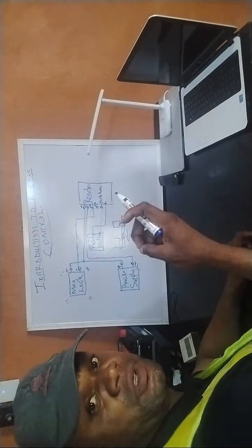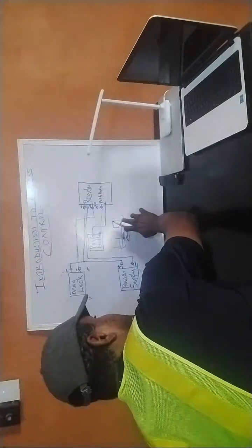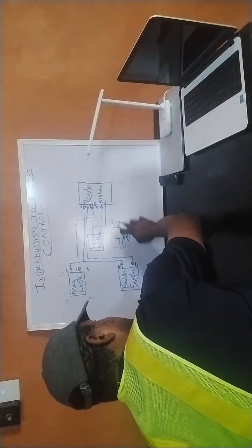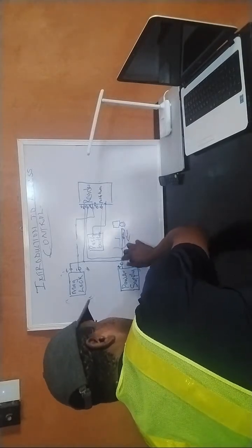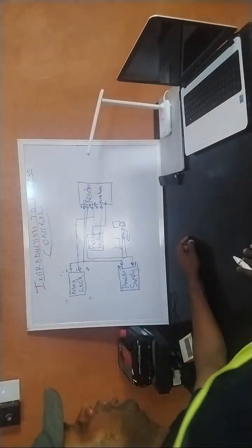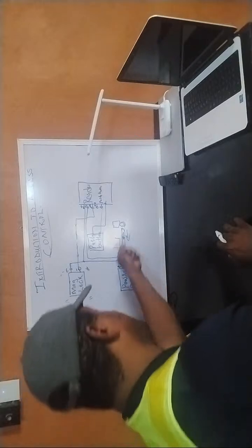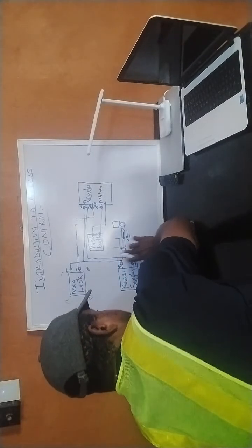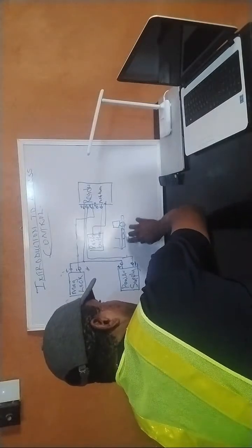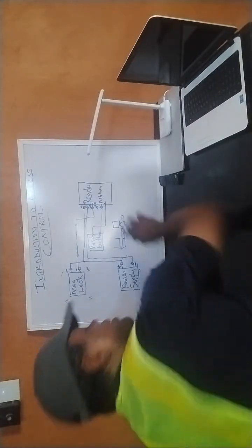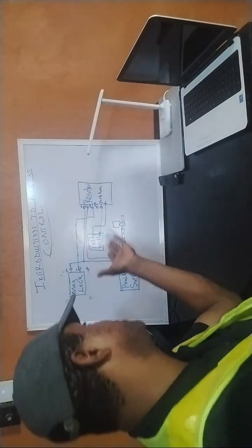For those few seconds that it is pulled out, it's no longer in this place. When the counter elapses the time, this one is pushed back, it returns and goes back into this. So that's how it works for strike lock and mag lock.